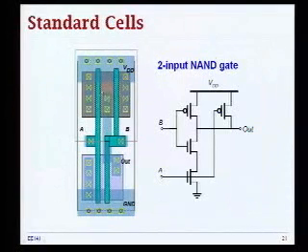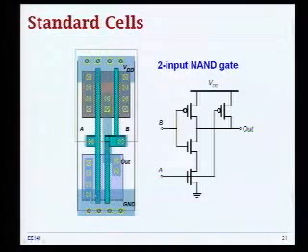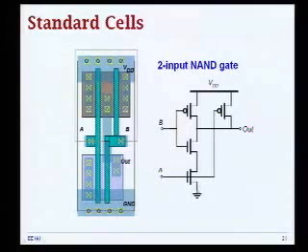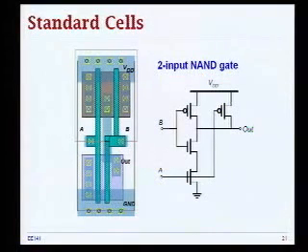So you clearly identify the PMOS transistors basically over here. So you have one PMOS connecting, this is the VDD, this is the output, this is another PMOS that's controlled by this gate signal B, and then you have two serially connected NMOS. So you have the common ground over here, and then that's this point. And then you have the drain of this transistor controlled by this A shared with the source of this transistor, which is controlled with this gate signal B, and then finally you arrive at the output over here. And again, you have all this nicely aligned such that when you put the cells together, everything fits nice and snug. So you can put them together.